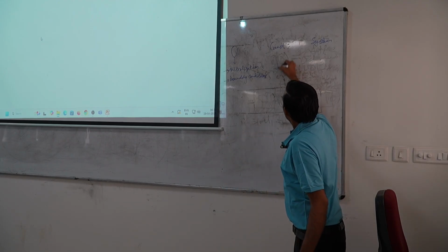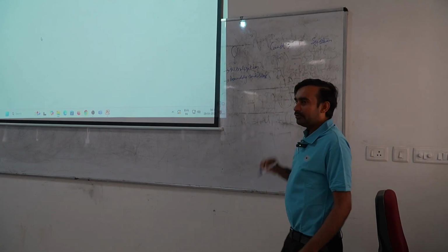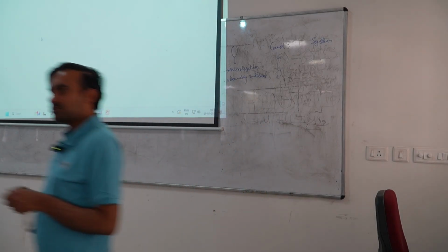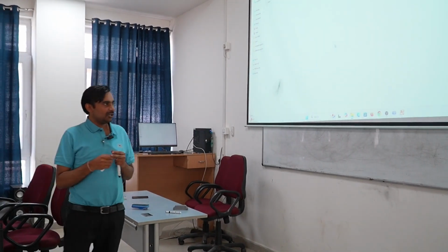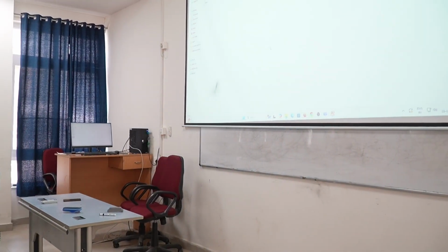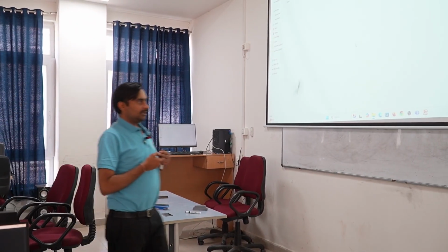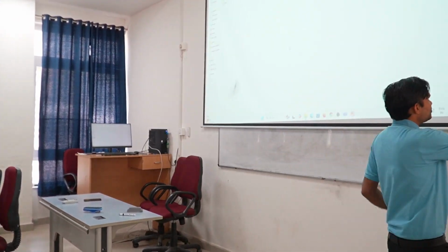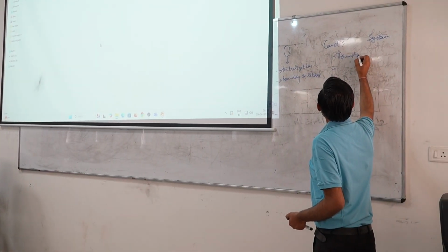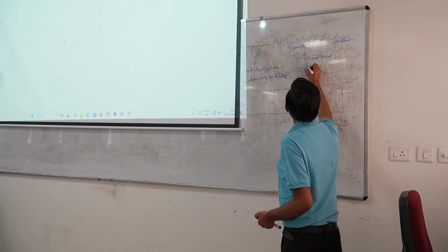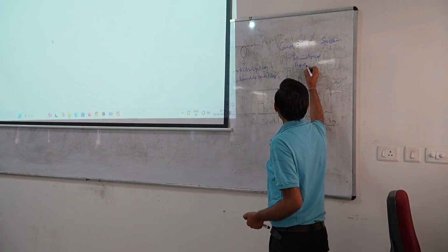Then we have the constant folder. Typically the constant folder contains the data which will be remaining fixed during the simulation. So what are the quantities typically remaining fixed during the simulation? We need to specify over here all the thermophysical properties and their associated models.